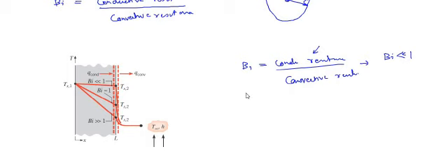And this is the case when we can actually use the lumped heat transfer approach, because in the initial introduction to the lumped heat transfer approach itself, I told that it can be used when the temperature gradient is actually not present, or the temperature gradient is very small. So when the temperature gradient is very small, the lumped capacitance method can be used.